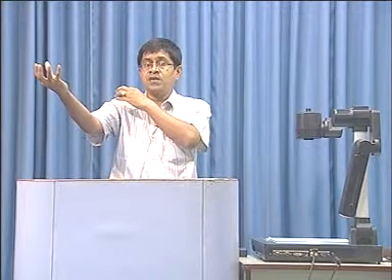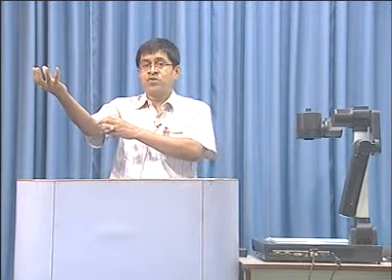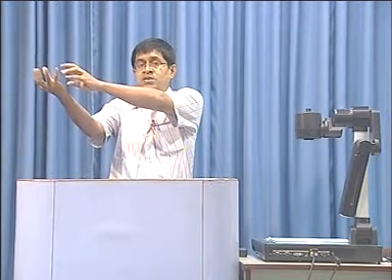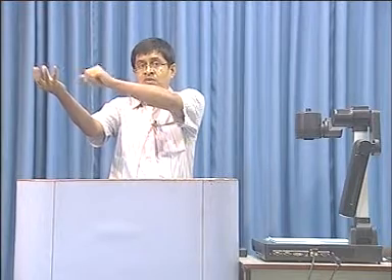Now it is in a stationary position, that means it is not moving, right. So, what are the torques to be applied at my shoulder, at my elbow, to be able to hold the object? That is what we call a static equilibrium, and the torques which we calculate are those to maintain this object in stationary conditions. So, that is the problem in statics of robotics.